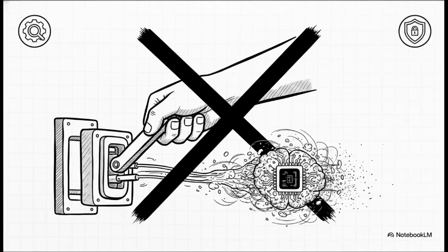And finally, the single most detrimental mistake you can possibly make: never, ever blind power cycle a tripped drive. Seriously, do not just walk up to the main disconnect switch and yank it off and on hoping the problem magically goes away. When you do that, you force a hard reset that totally wipes out the immediate context and clears the drive's active memory. You are literally destroying your own best diagnostic data.